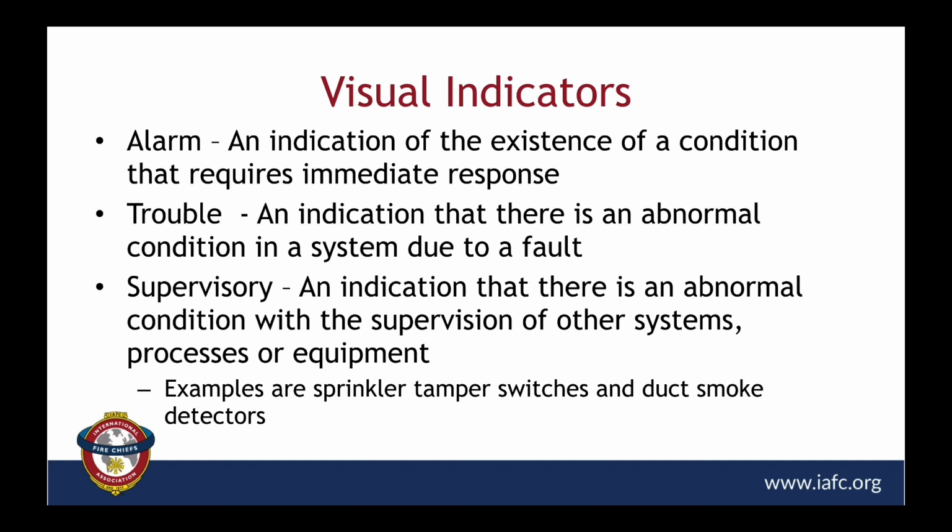Next slide. I think, Dan, too, Mike, if I can just add on, right? If you're a responding engine company to maybe a water flow alarm, so you get there, there's horn strobes going off, people have evacuated the building, and you go to the panel, right, as part of that first in assignment. If you scroll through or the indicator lights are on for supervisory, gate valve closed, or something along those lines, that's starting to piece together this investigative picture.